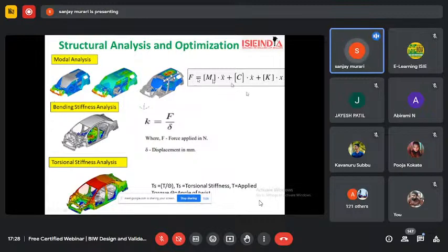Here we calculate the strain energy. Wherever the strain energy is more, we try to provide stiffness, and if we increase the stiffness, we increase the natural frequency. Similarly, wherever the strain energy density is less, there are chances of optimization. There we can have cutouts and reduce the material, and scale down the natural frequency, so we can get our target natural frequency. The stiffness required to get this natural frequency is called the modal stiffness.